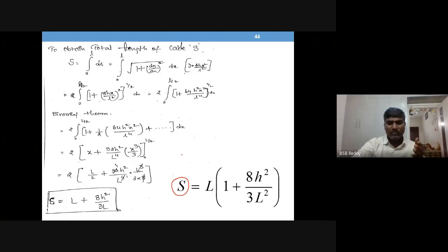What you will be given, or you will know in the question, or practically, is the distance between the supports, which you are able to measure, and the sag value of the lowest point. You can measure it with the latest surveying equipment, where the levels or the coordinates of the points can be easily measured with a total station and the latest technology available in surveying.